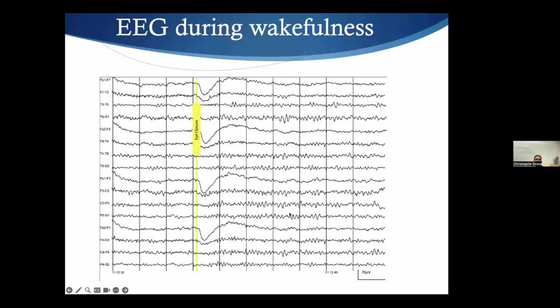So this is EEG awake, where you see here the eyes closure. So this big eye blink. And I'm mentioning this because this is important when we do analysis, whatever the analysis, because for eye blinks we have good tools to remove them, but an eye blink is very high amplitude compared to many other signals of interest. So it's easily 5 to 10 times larger compared to, for instance, the evoked potential.